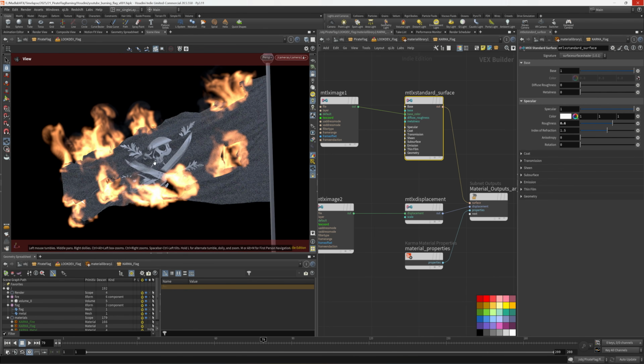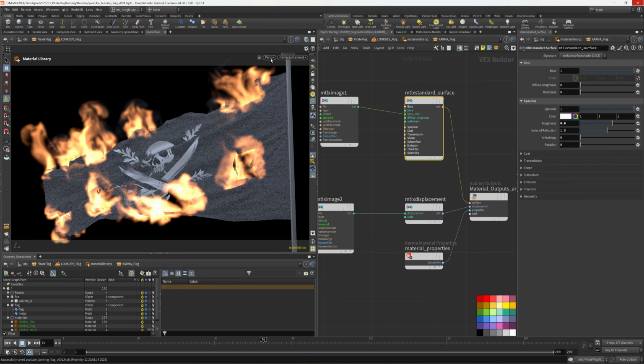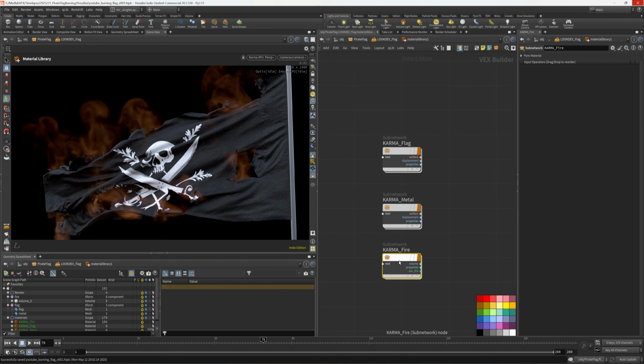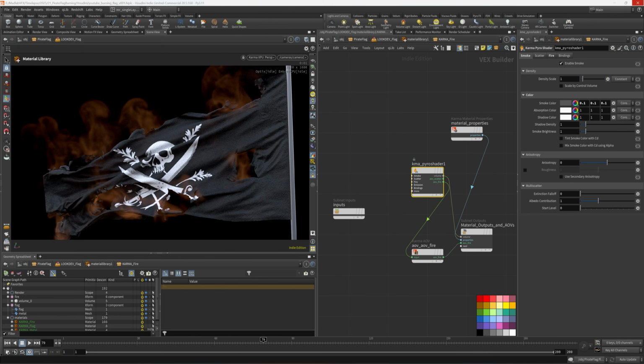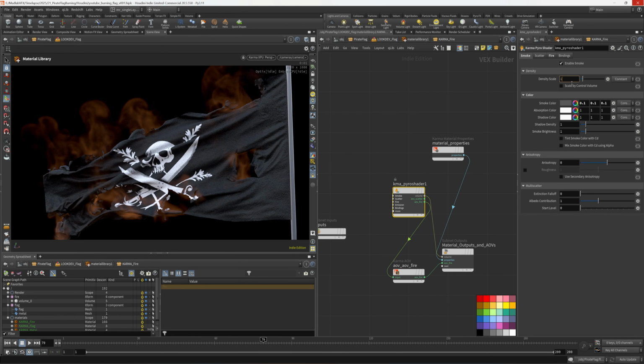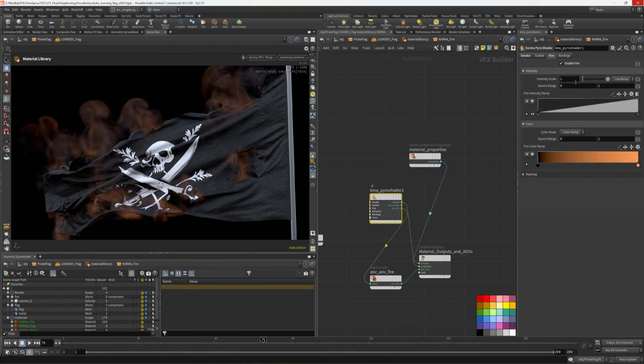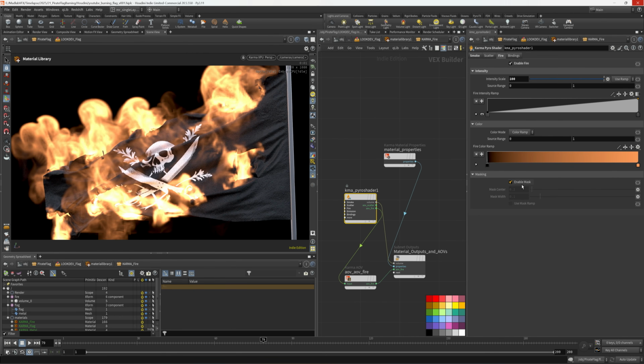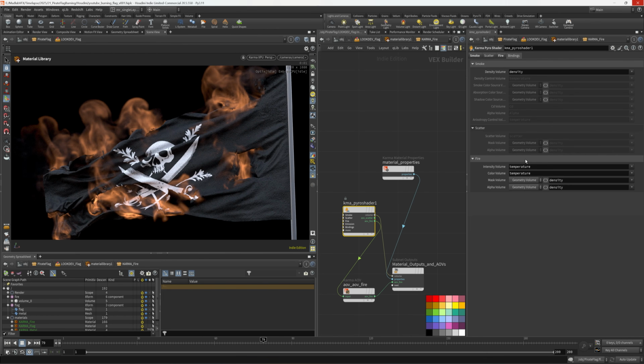Let's go back to the camera position here and see the shaders of the fire. Adjust the shader of the fire. Let's increase the density of the smoke by 10. Okay. For the fire, we need to increase the intensity of the fire like 100. Too much. But you can use masking here, enable mask. And here in the binds, we can change the intensity volume for the flame field instead of temperature.